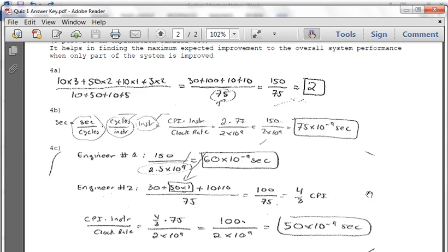And then going to the architecture process, if enable equals 1, then F maps to A. Else output what? For a tri-state buffer, if the enable signal is equal to 0, what are we outputting? Yeah, high impedance. So if you can do that, then you're good.